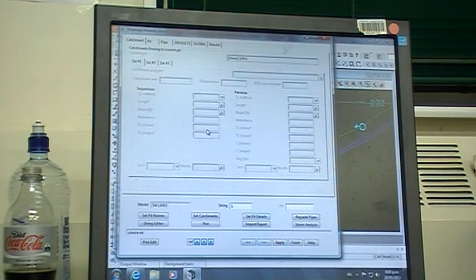So every now and then we have to allow for it to surcharge through a grill and end up as overland flow, and so I will manually work out how much I want to pull out at different points and redirect into other parts of a reticulation system. And this is the kind of place I can do it.